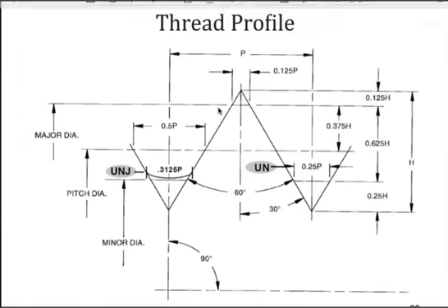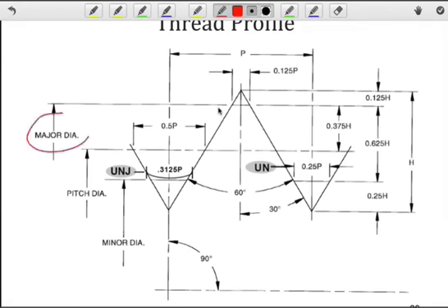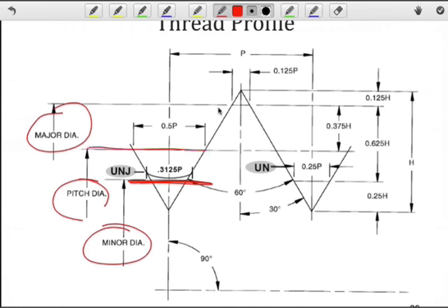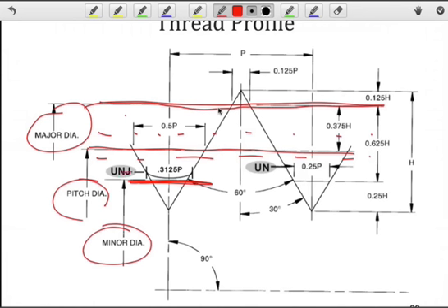So if we look at the geometry based on those parameters, we're going to see something like this, where again your thread tolerances relate to major diameter, pitch diameter, minor diameter, and we're looking at a side view of the thread with these locations on the thread. So we get some type of tolerance on these, some type of allowance for the location of those diameters.